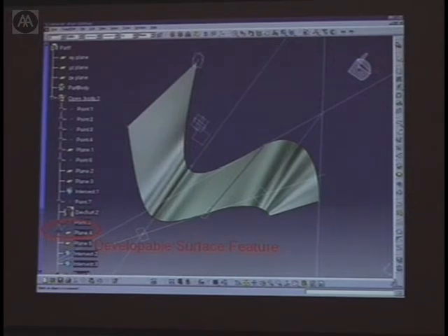So this is where the idea of toolmaker comes in. This is some of the work that we do on the side, besides working on the project: solving project problems by working as an architect on the projects themselves. In this case, I worked with a colleague of mine, Dennis. I took his picture and made that into the icon for his tool. Basically, if you design a NURB surface, and in this case it's a mathematically constrained NURB surface, where we constrain a particular polynomial across the so-called knots of the control points, you can actually get this thing to always behave in a single direction of curvature.